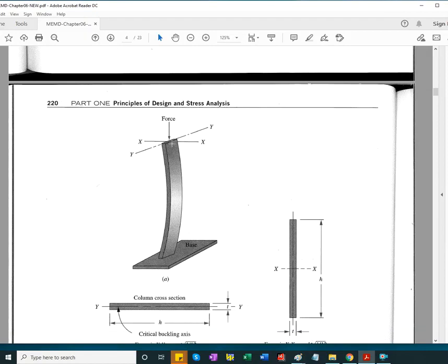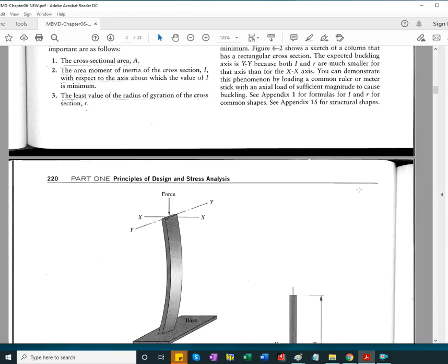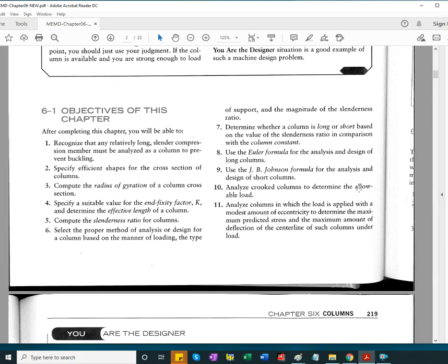It's easy to run tabletop experiments about buckling. Just take a slender ruler and apply compressive longitudinal forces, and you'll see that it buckles in the X plane for this arrangement. If it's simply supported here, with possibility of rotation, and here you push it with your palm, say, and allow again for a slope to be other than zero at the end.